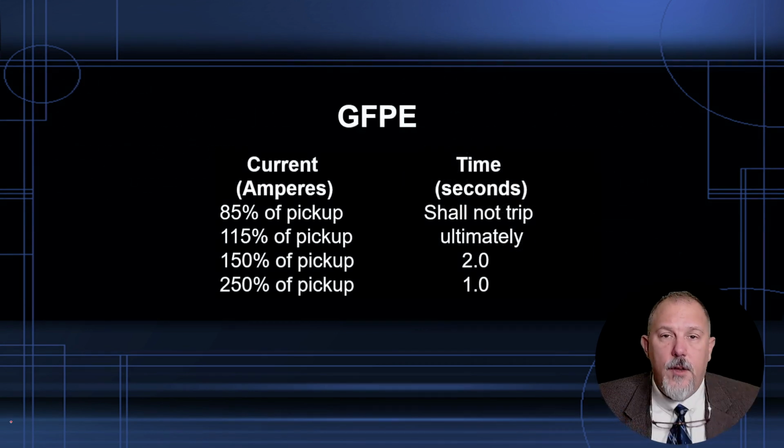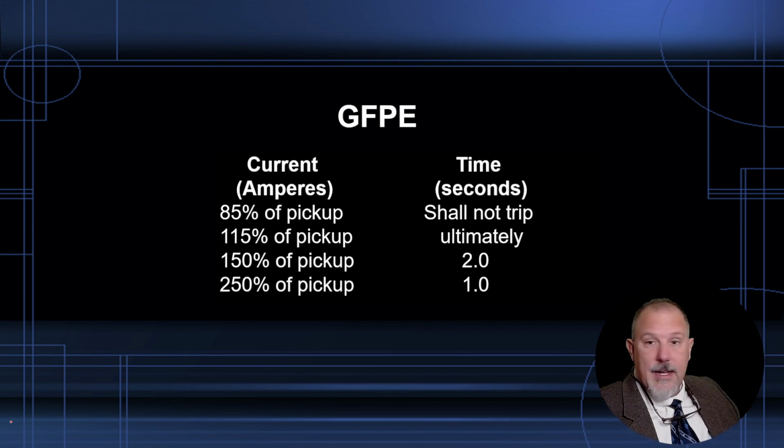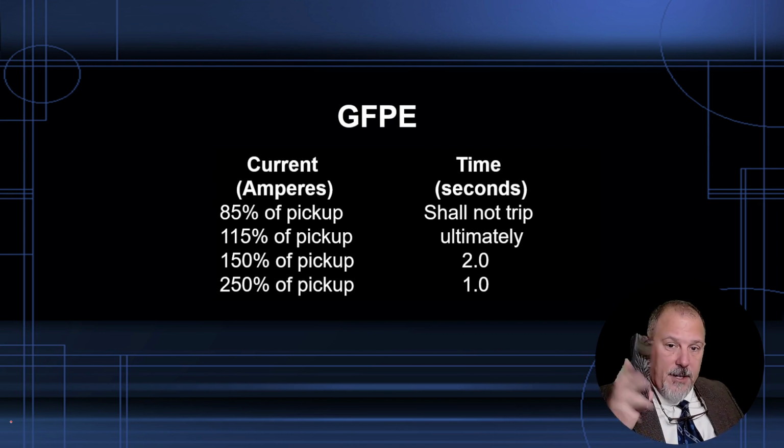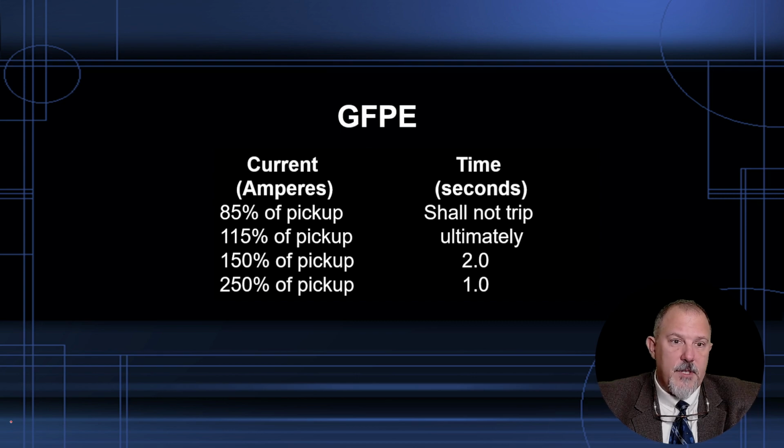In fact, GFPE, the way the standard is set up, 85% of the pickup level. So let's take a 100 milliamp device. It shall not trip at 85%.